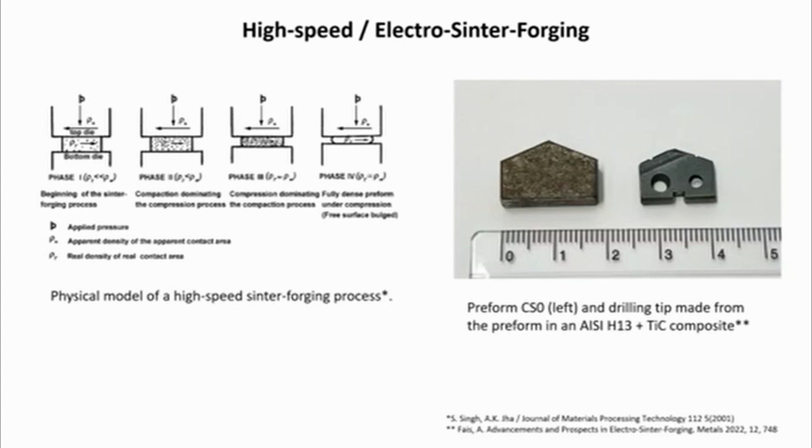During the last few decades, high-speed working of materials has occupied an important position in industry, as it has been used successfully in producing engineering components at competitive rates. The deformation pattern during the high-speed sinter forging process is influenced by several factors, which interact with each other in a complex manner. The decisive factors are the density of the preform, forging temperature, lubrication condition at the die-workpiece interface, the flow stress of the sintered materials, and the factors related to the forging equipment such as deformation speed and contact time under load.